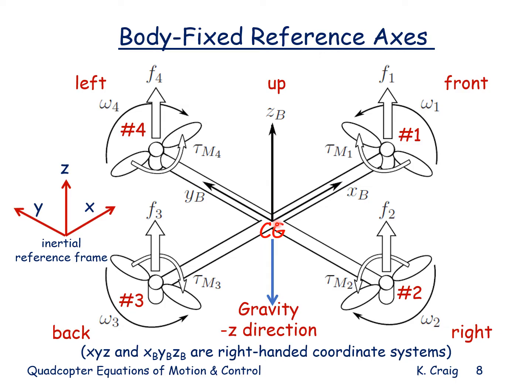The thrust forces, and there are 4, 1 for each motor propeller, are F1, F4, F3, F2, and they are in the positive z sub b coordinate direction, the direction of the body-fixed z-axis on the quadcopter. The combination of these four forces give the quadcopter its thrust.